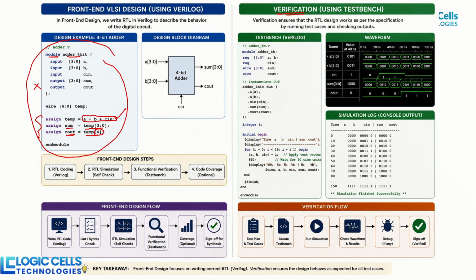After writing the Verilog RTL code, we need to simulate it, right? Before we write an actual test bench, the designer will write a very simple test bench and check. Then we will write a SystemVerilog or UVM test bench to verify the functionality in detail. That is your functional verification stage.